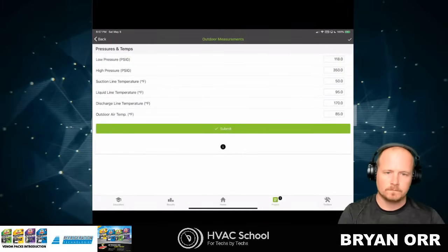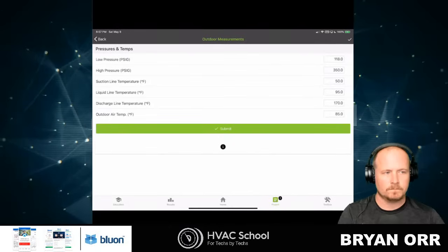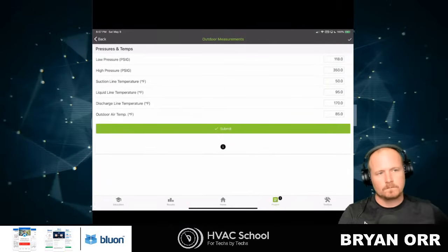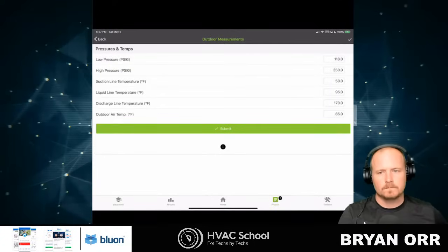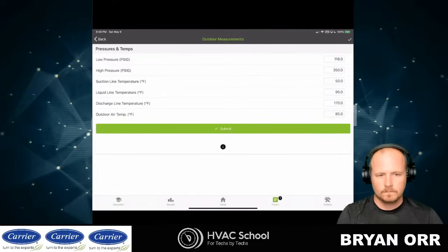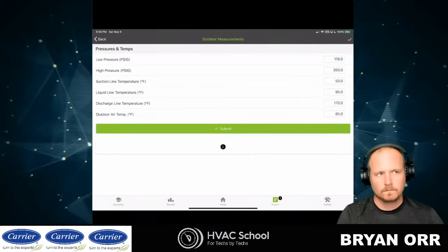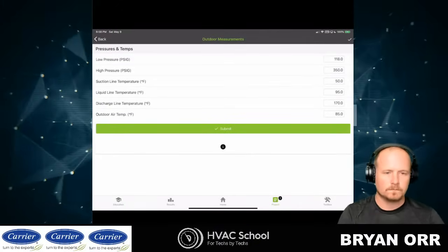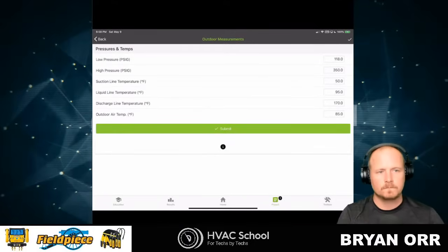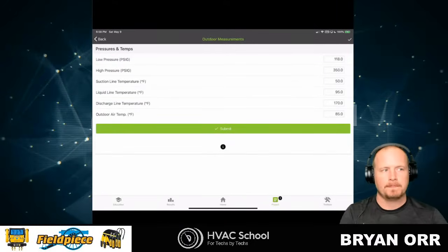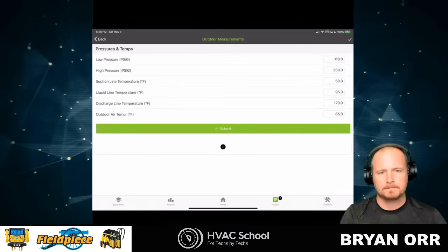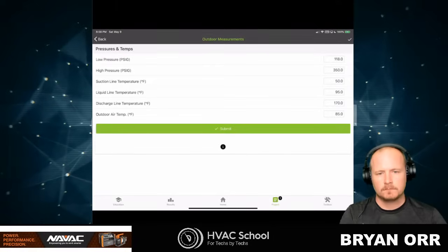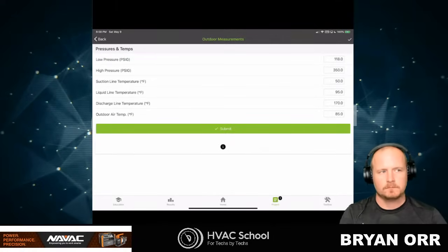And the other cool thing is you don't have to break the bank. If you own a handful of probes and you want to use those in MeasureQuick, you can use those, and then the other readings you can manually input. So it's not like you have to have everything or nothing. You can use what you have and then add to your toolbox as you go, and eventually you'll find out, boy, you want to have everything streaming data in because it's so much faster. But it's not required. And if you're in a trade school or whatever, your kid learning, and you're using analog gauges, you just want to use the diagnostics, you can input all the data by hand.